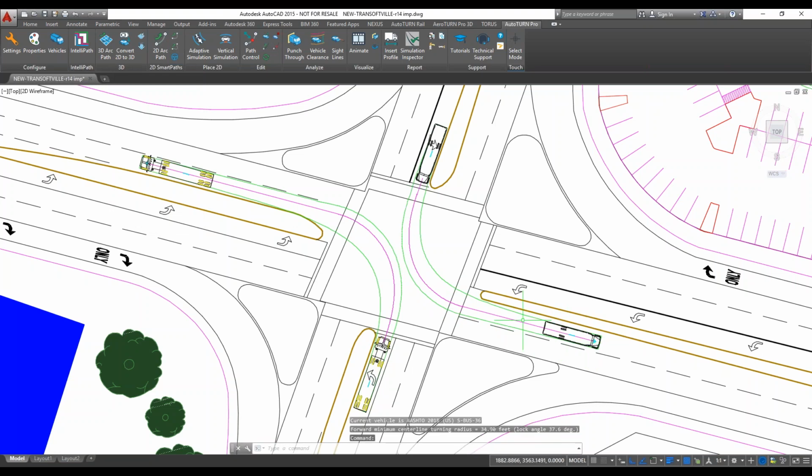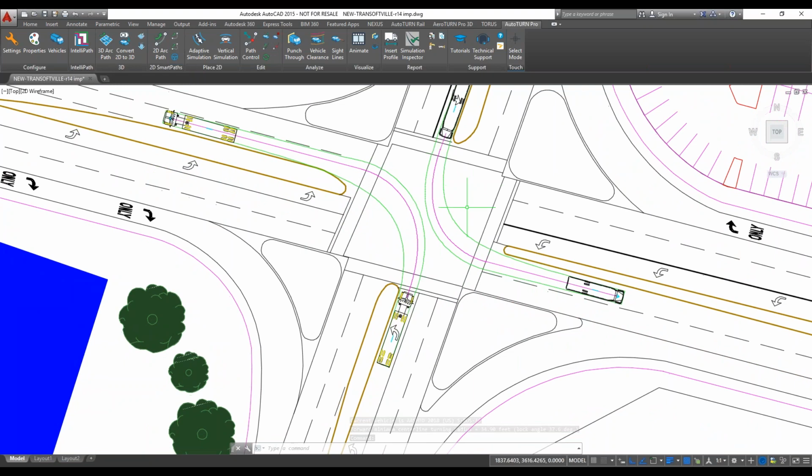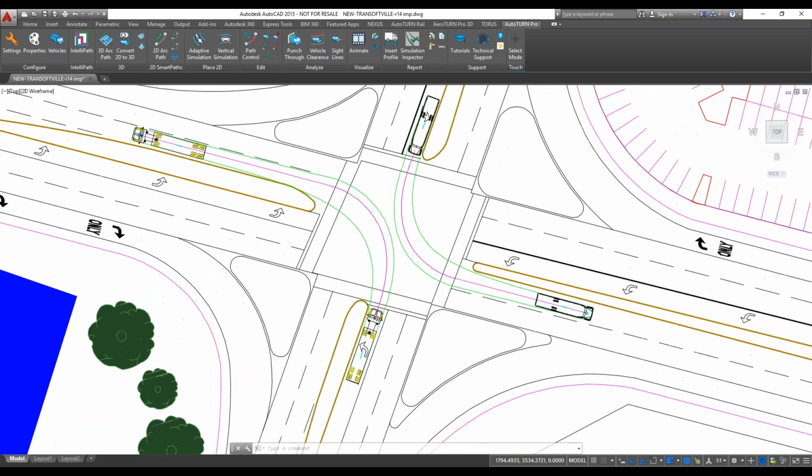Okay, so large vehicles will likely use corner path to generate these maneuvers. If we're using a larger, or even a larger vehicle, say a WB62, we know that vehicle is going to oversteer. Right now, if these are our road conditions and these are the design vehicles we need to support for opposing turns, then all we need to do right now is check a clearance for the body envelopes, make sure they work.